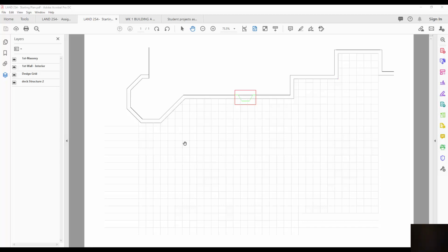So this grid pattern is a 2 foot by 2 foot square, which equals 4 square feet, and therefore it's very easy to calculate our 1,000 to 1,500 square foot requirement. In the upcoming lessons, we're going to learn about how this layout is affected by the site analysis. So where the sun rises, sets, where are the prevailing winds, what are the views, things of that nature.